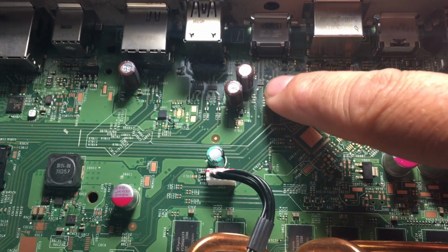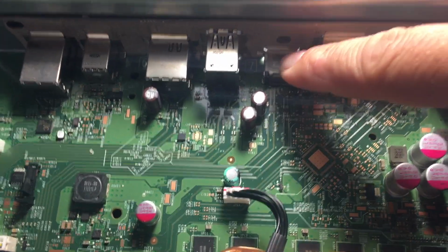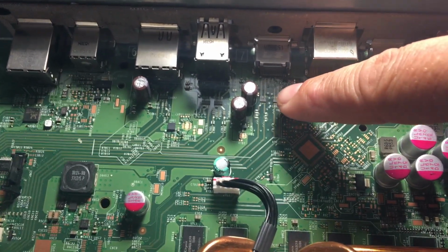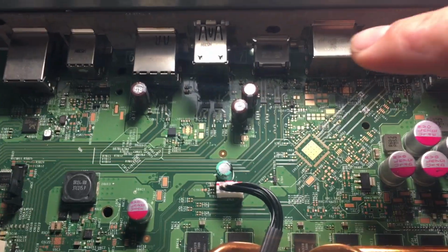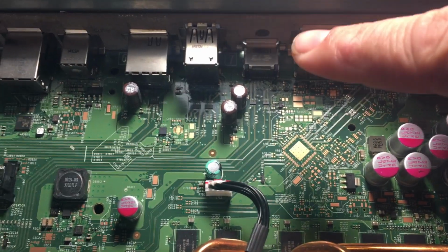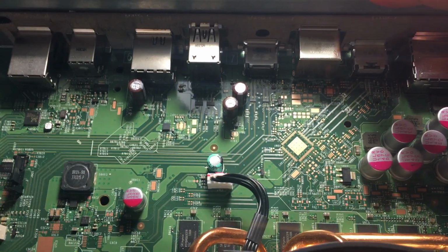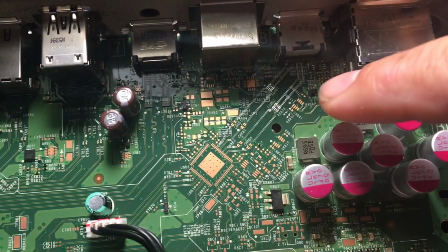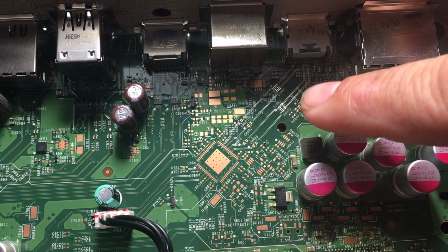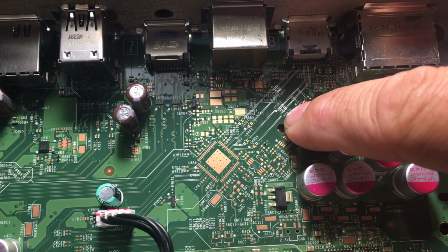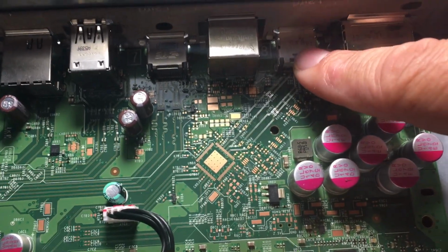They're ESD EMI filters. So they go right from this outlet. There's nothing here, but basically the cable runs from here to these ports, and they run to the video chip of the Xbox One, and they prevent a shock or a surge from the TV destroying the video board of the Xbox One. And you can see here, this actually works pretty well. On the input port, these silver solder points are where I removed the ESD filters from this port here.